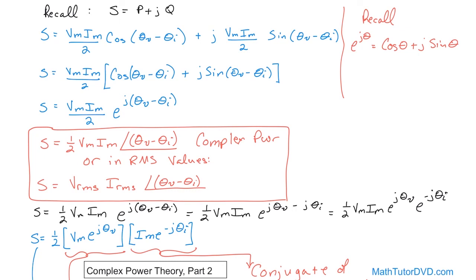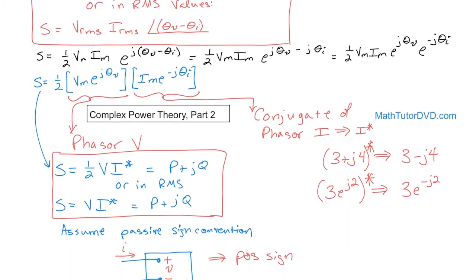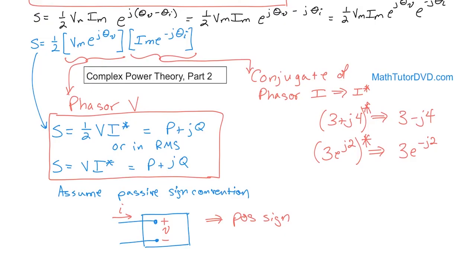If I am given the voltage and the current amplitudes and their phase angles, I can formulate a phasor like this where I subtract the phase angles and I calculate a phasor and I'm going to get the quantity like that. Now sometimes things might be given to you that this is actually easier to do, okay? But in most cases it's going to be easier for you to just know the voltage and the current through something, and you're going to multiply this times the conjugate of I, and you'll find that'll be the complex power S. And in other cases, you'll use that triangle that I showed you in the last section, because that's functional and very easy sometimes to use as well.